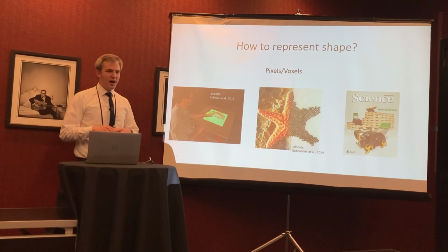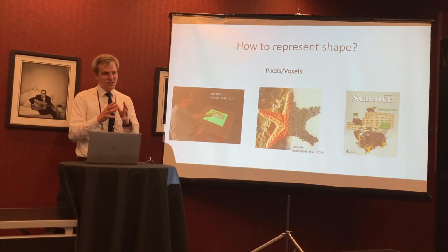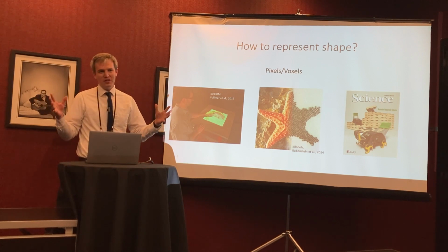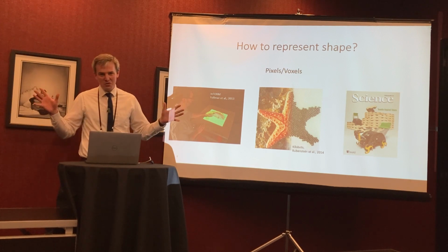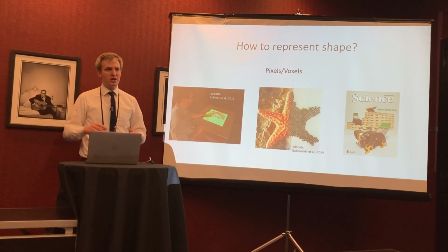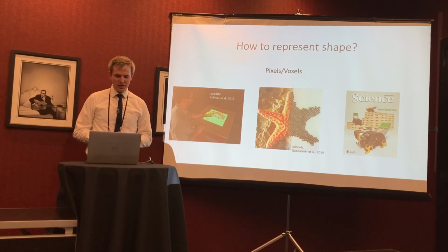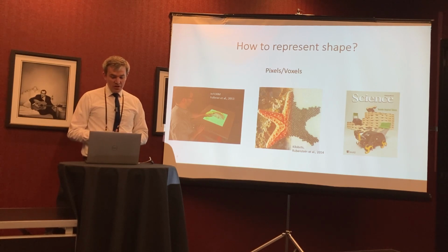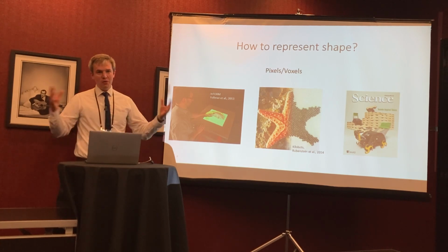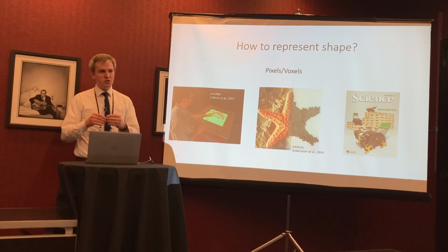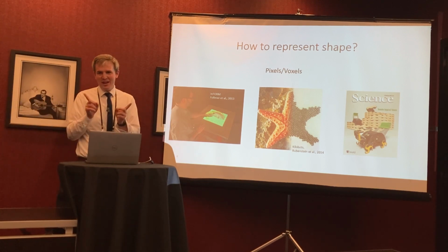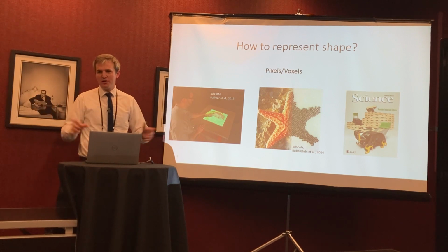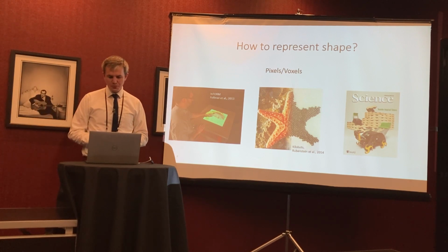One is that if I want high resolution in one spot of the robot or of the image, I need high resolution everywhere on the image. So if I want fine details in some spot, I need to put a whole bunch of individual shape-changing elements across the body of the robot. Another challenge is that there's often a trade-off between the degree of shape change and the resolution of the shape change. So if I want my robot to be able to stretch really big, I can't have hundreds of little tiny pins that are going to stretch really big in each direction.